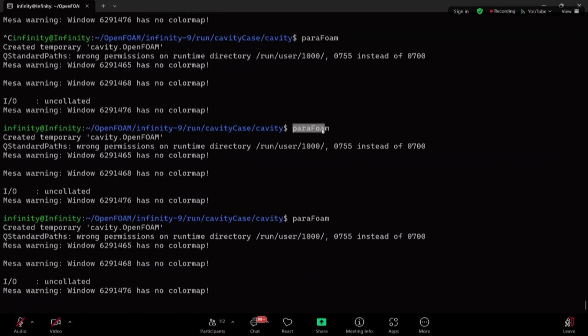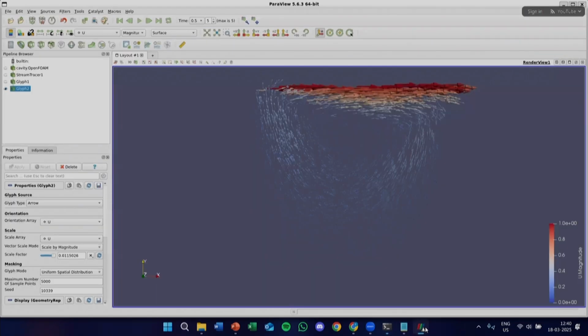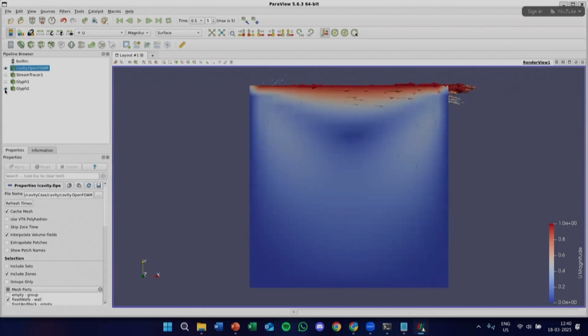So all this is in the same cavity folder, right? Yes, everything is in the cavity folder only. Okay, it's showing no such file or directory. You mean blockMesh, icoFoam, and paraFoam all need to be done separately? Yeah, the commands are all separate. In the bash, blockMesh is showing no such file or directory. You'll have to check whether your directories are proper and you're in the proper folder.